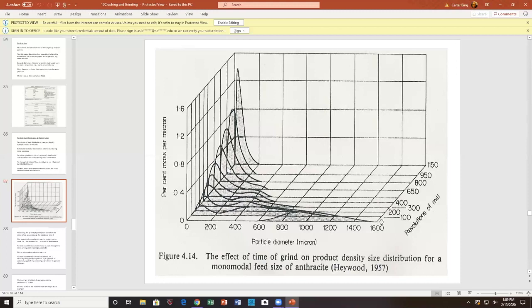Just because you have grinding doesn't mean it can also not agglomerate. This is particularly true if you're self-grinding material. Material will break down, go to a certain size, after which, because of static electricity created during tumbling, the size may actually increase. Pretty funny. It says tumbling, but actually it's an agglomerator.